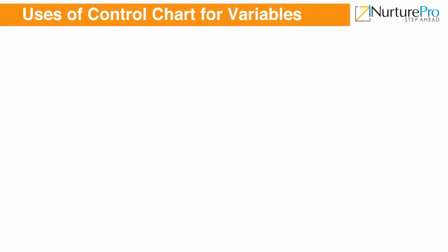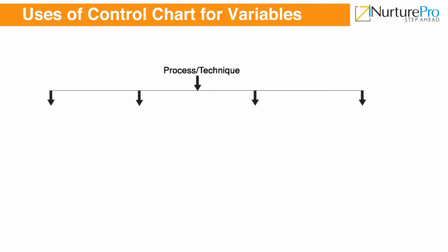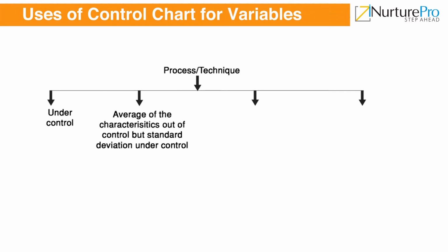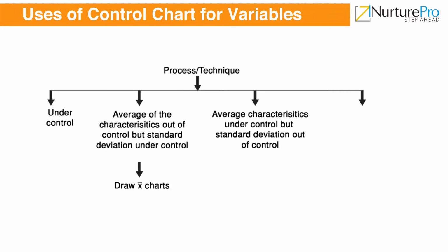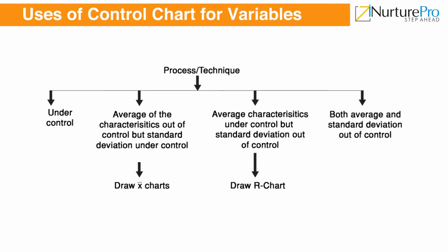These charts are used for measurable quality characteristics of all products, which are divided into groups. These groups are considered as samples having a fixed number of components selected randomly for testing. Then, the mean and standard deviation of the quality characteristic for each sample are calculated. Next, let's look at the 4 most commonly used control charts for attributes.